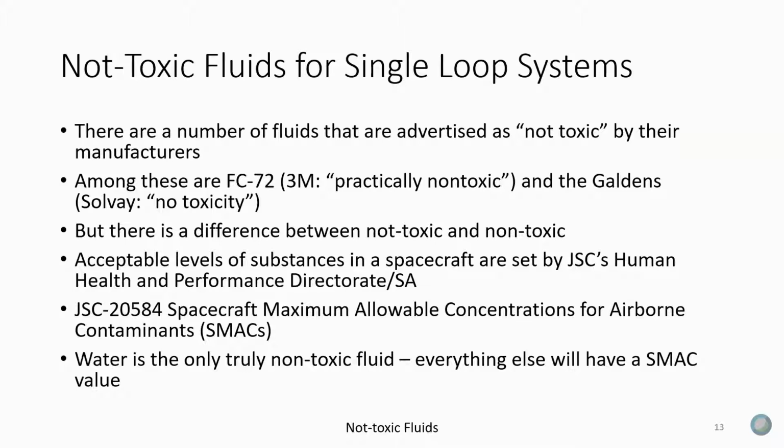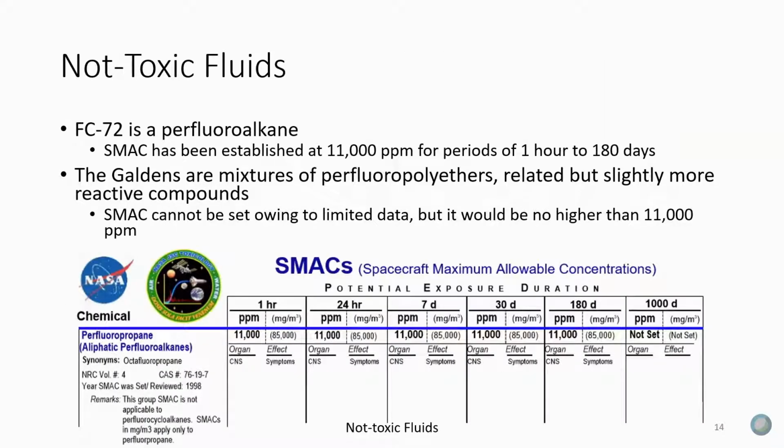But saying that, none of the fluids that we're talking about here are particularly high vapor pressure. Even ammonia is about 4 atmospheres at 4 degrees C. So it's not particularly high pressure. And so it's within the realms of pressures that we're not really particularly worried about in terms of tube wall thickness.